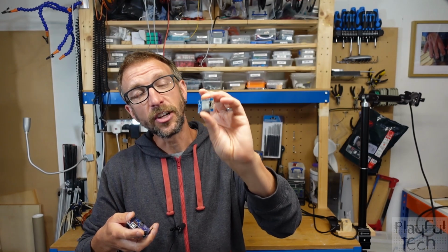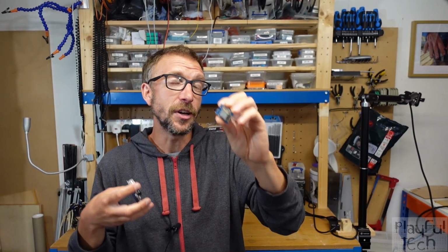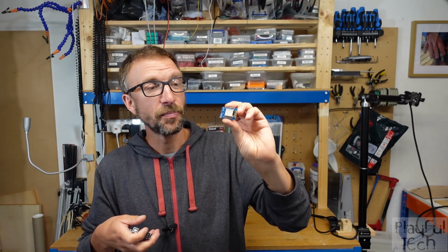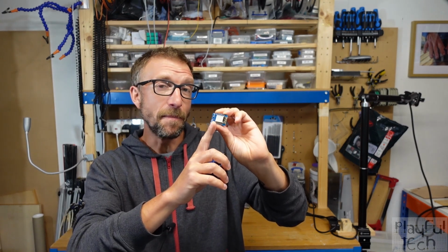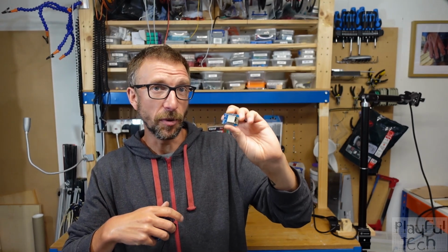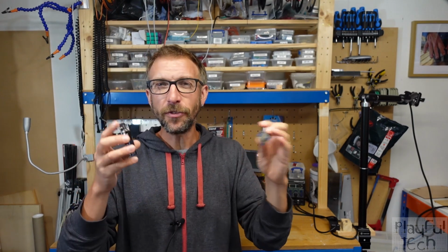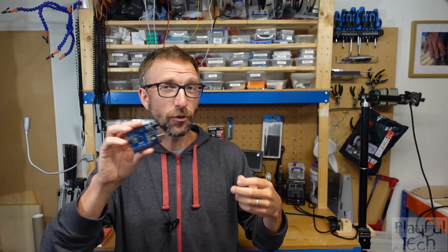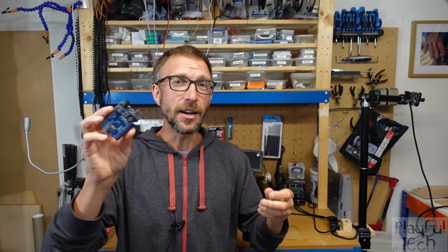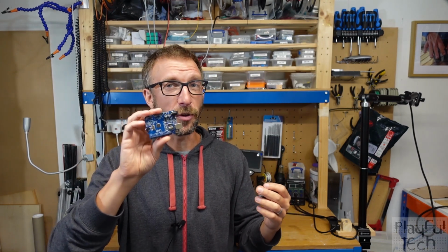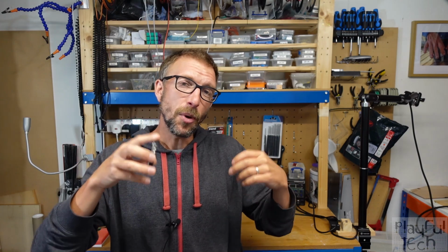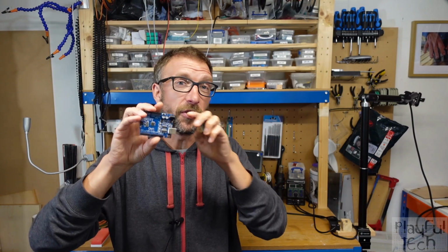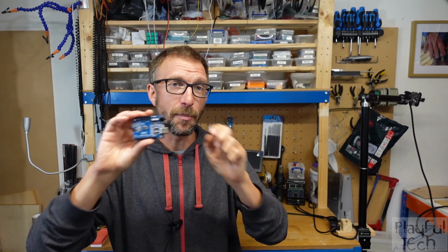Newer devices, such as an ESP8266 or ESP32, operate at 3.3 volt logic level. So that means that a high signal for them is only 3.3 volts above ground. Now there's actually a bit of tolerance in those measures. On an Arduino Uno, any voltage above 3 volts will be treated as high, while any value less than about 1.5 volts will be treated as low. But when we talk about the logic level, we're referring to the top end, the ideal value that would define a high voltage at that pin.